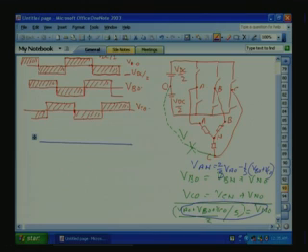Our omega t starts from here, that is what we said here. If you see the 60-degree interval period, that is this one, there is a change in pole voltage every 60-degree interval period. So, VAN will be stable for a 60-degree interval period, and every 60-degree interval it will be changing.